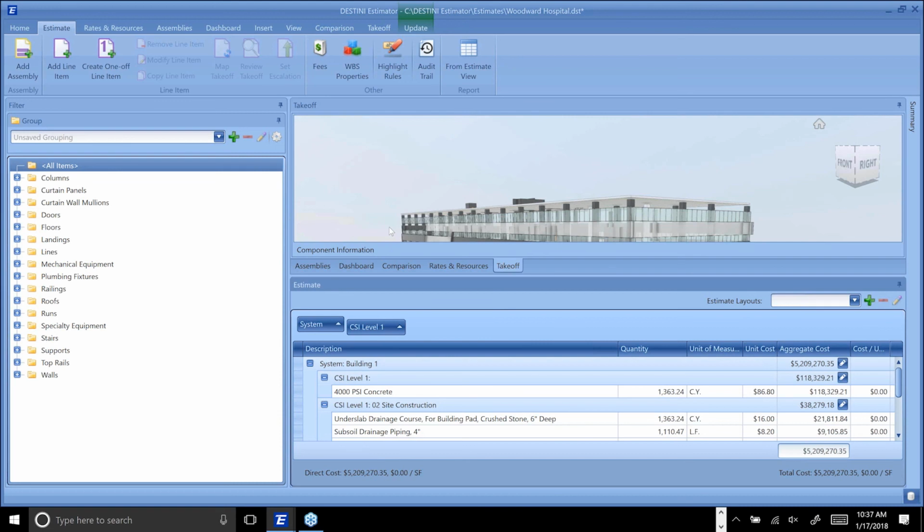If it's the stump the chump kind of question, one of the things that we do run into often is that those database IDs and GUIDs can actually split. So if you have a model where one object turns into two, let's say I drew a slab and created a split between those things to represent different pours, we actually go through a significant amount of effort to make sure that we track that. So when you have the updated model, you can see that this is the same object, although it has been split into two different objects, and we will represent that and show you that that is what has happened.